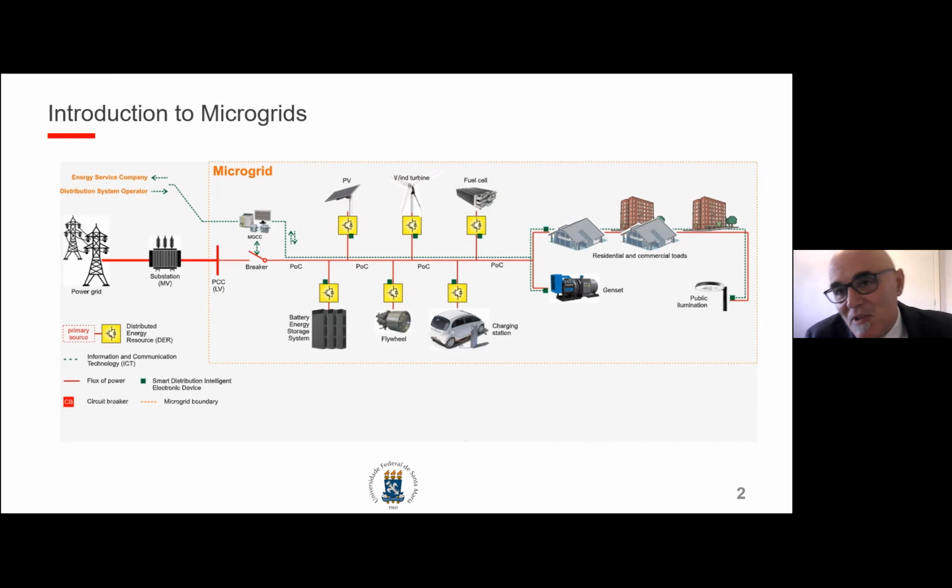In my case here, even in Brazil, a developing country, I have solar panels, 5 kilowatts peak. I'm not planning to have a microgrid here, but if the ingredients are here, if you have a battery energy storage system and you have the PV generation, why not? So what is missing? I need an additional microgrid central controller, probably a circuit breaker, some communication network.